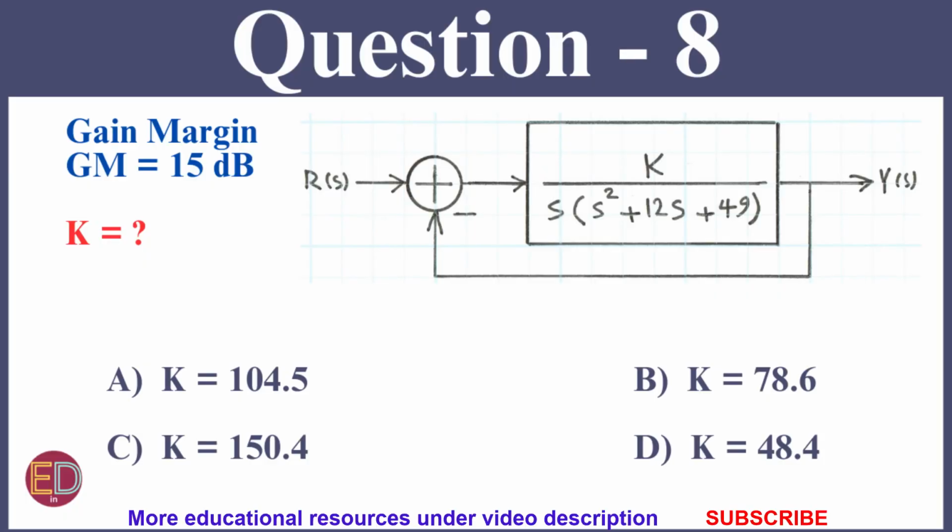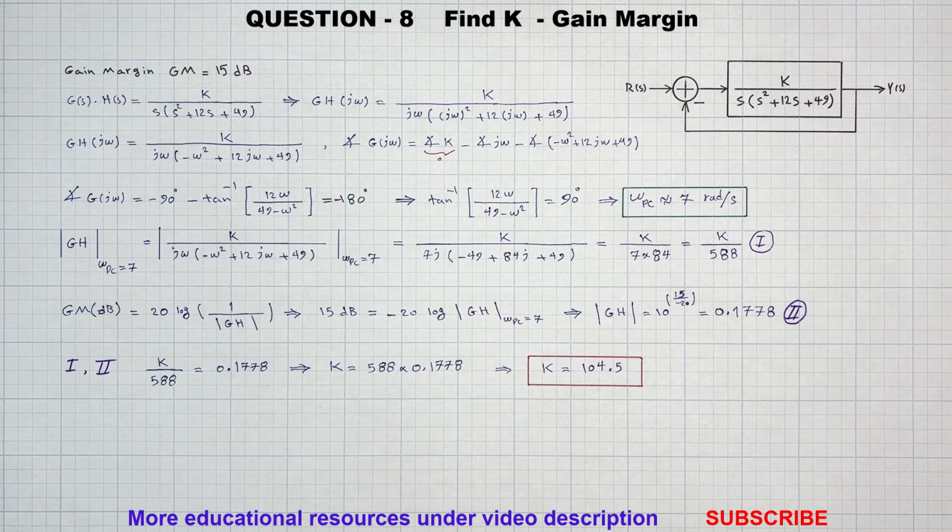Question 8. For this unity feedback control system, we need to find the value of constant K, which makes the gain margin 15 dB. The first step is to determine the phase crossover frequency, omega PC, by setting the phase of the open loop transfer function G H of j omega to minus pi, or minus 180 degrees. Since we have a unity feedback, H equals 1. So the phase of G of j omega is given by this expression.